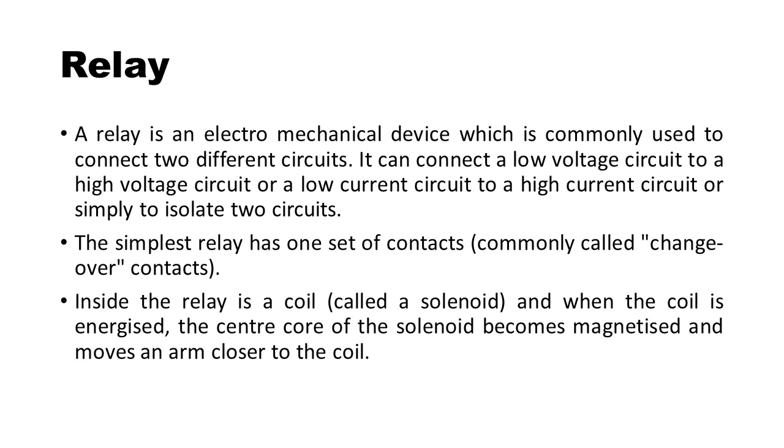A relay is an electromechanical device which is commonly used to connect two different circuits. It can connect a low voltage circuit to a high voltage circuit, or a low current circuit to a high current circuit, or simply to isolate two circuits. The simplest relay has one set of contacts, commonly called changeover contacts.